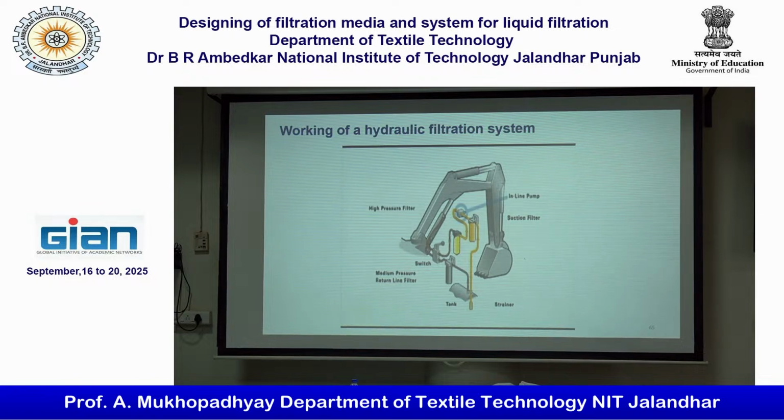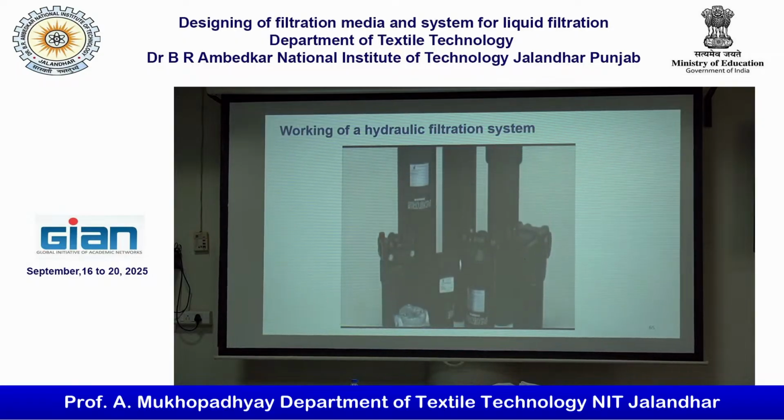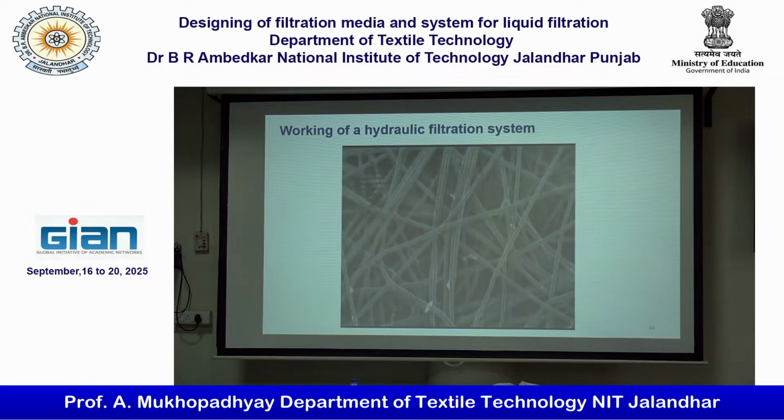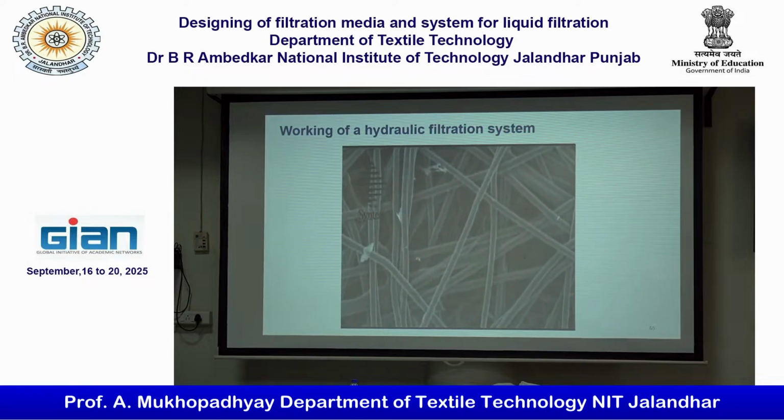It is then filtered again in the high-pressure section of the circuit. This second filtration is to protect the expensive hydraulic components, the muscles of the system, from particulate and debris. All of our high-pressure filters contain Donaldson Synteq synthetic filter media, specially developed by Donaldson for high-efficiency liquid filtration.